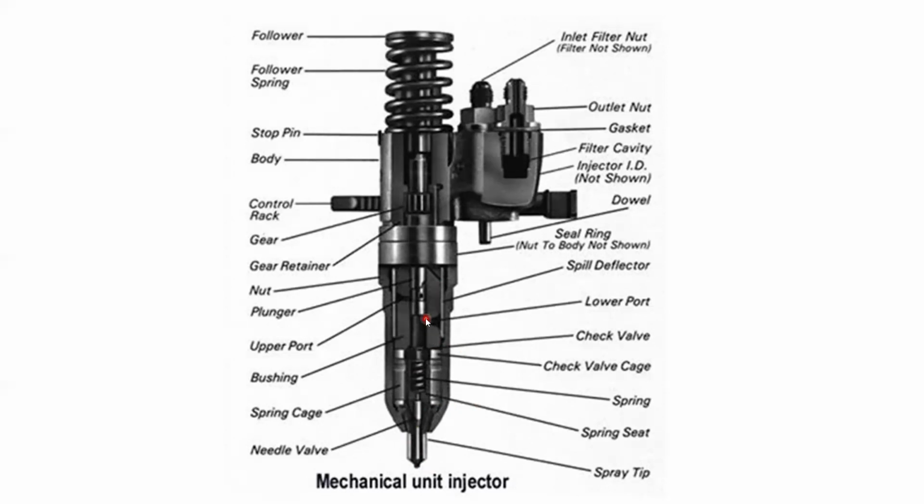A small amount of injector fuel goes through these, lubricating all of these moving parts. You can see why it needs lubrication, since it is a metal surface inside a metal surface, sliding up and down.